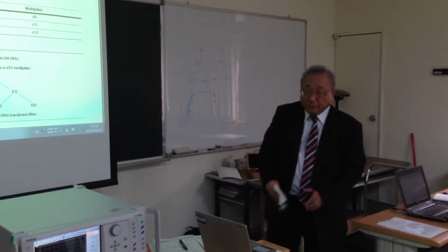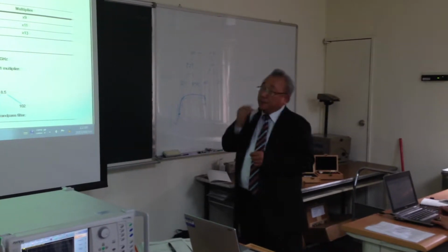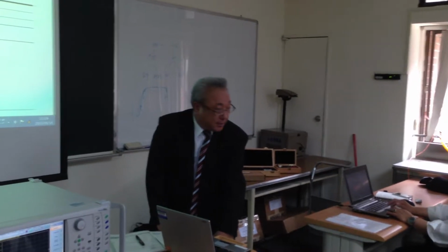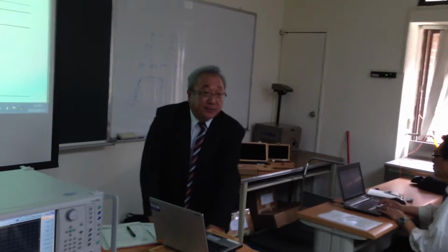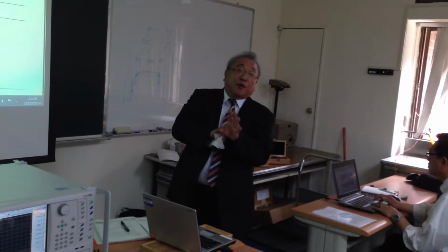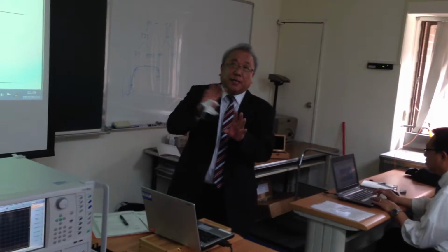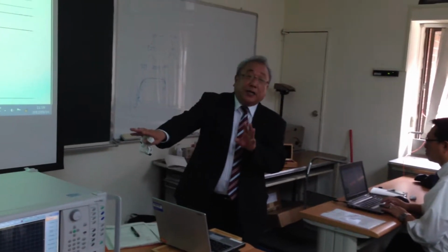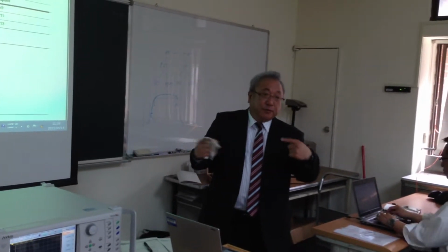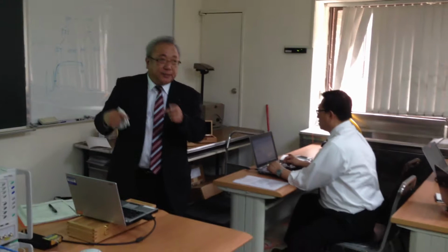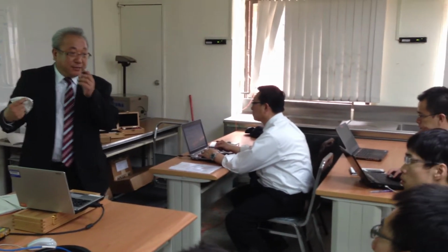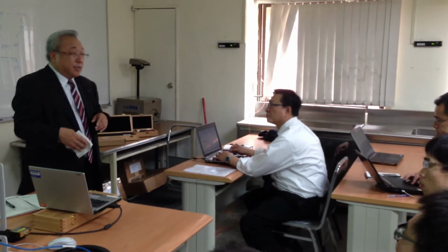Sure. Because we have to determine how to select the bandpass filter. We can calculate which frequency the image signal is at, depending on the local frequency and a multiplier number, and the mixer structure inside the VNA. So that is a little complex. I cannot say now how to calculate it, but that is an important thing.